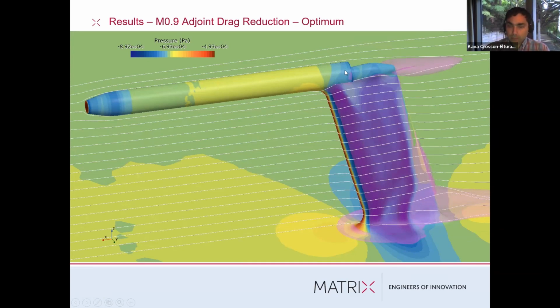So I think if I were to redo this, I would include the forward Pitot tube in the optimization. I guess I was a bit loath to do that because I didn't want to disturb the flow field at the front, but you could also monitor that pressure at the front and make sure that your design changes weren't modifying the read out static pressure.